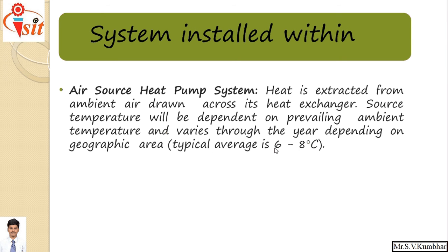So in this heat pump, heat is extracted from ambient air, which is drawn across a heat exchanger. Heat source temperature will be dependent on the prevailing ambient temperature and varies through the year depending on geographic area, that is typically an average of 6 to 8 degrees centigrade.